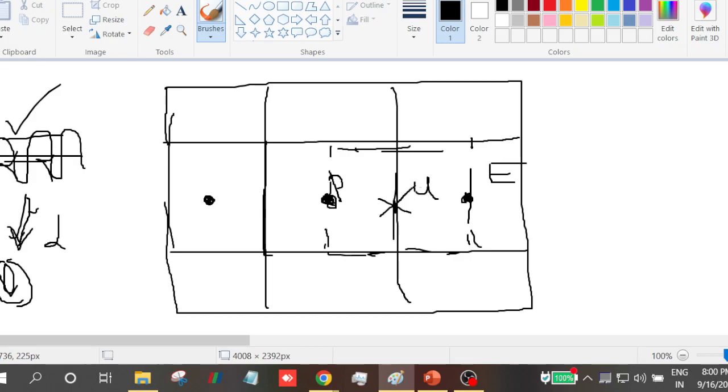It's everything to do with the storage only. Similarly we do for y. We store the v at this north face, so that when we go d p by dy, we need it at the north face and the south face. So I'll make these centroids only as the north face by making a different control volume. I hope that is understood. That is the way in which we go about. So we store it at different points. So if there are no other queries, you can leave the meeting. Thanks for attending.